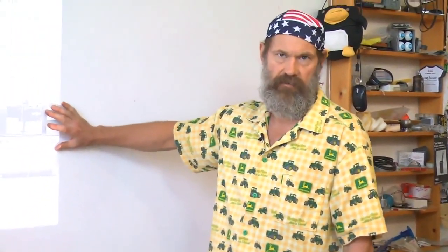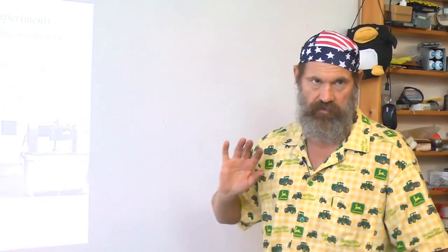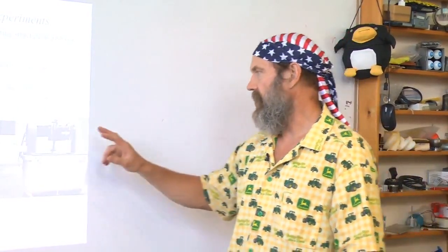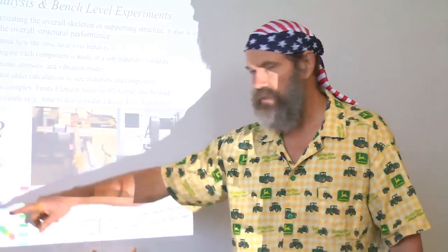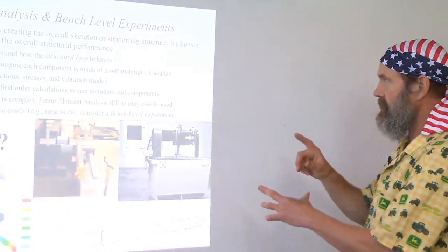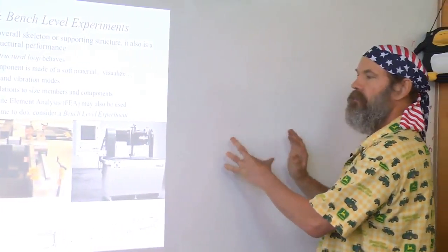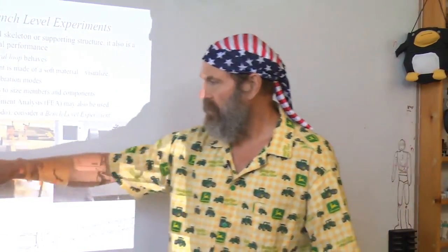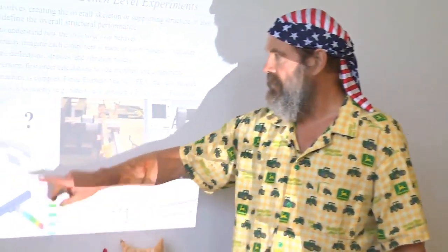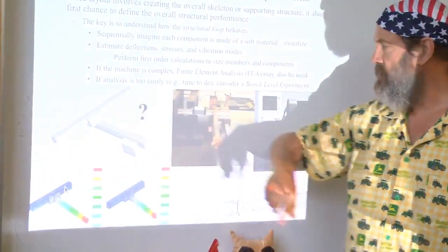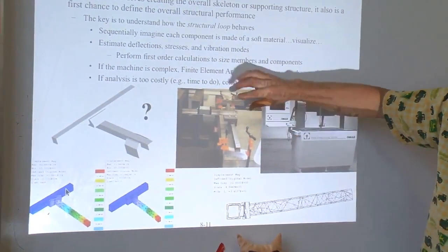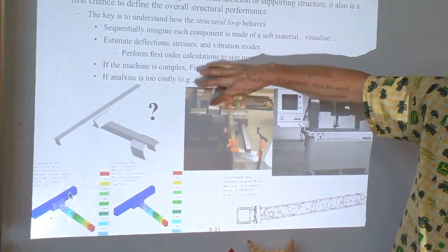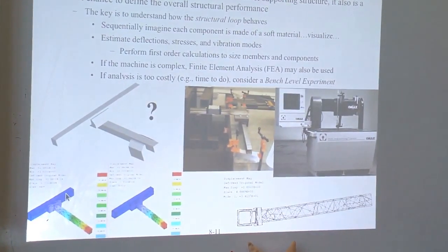Turns out for this particular small machine, we chose not to do that. We used a different kind of bearing within extruded aluminum because it came out a little bit cheaper and allowed us a modularity that we liked. But for very small compact machines, this would be the way to do it. And the lesson here is we went from concept sketch, first order analysis, solid model, finite element analysis to verify this type of joint structure, what the stiffness was, then a mock-up in the lab where we actually built one and did stiffness tests and dynamic tests to get our early results.